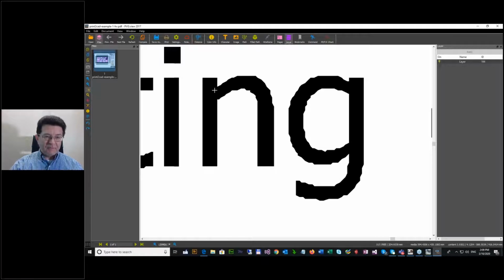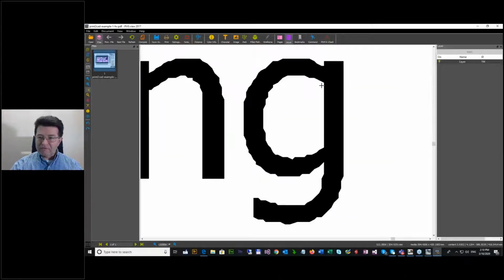This is another problem. Somebody was using fonts here that Adobe was not able to embed. And if Adobe is not able to embed fonts, then AutoCAD has to put this text as a boundary hatch. What you see is only a field path, a boundary hatch. And what is this one? This is a terrible PDF resolution.